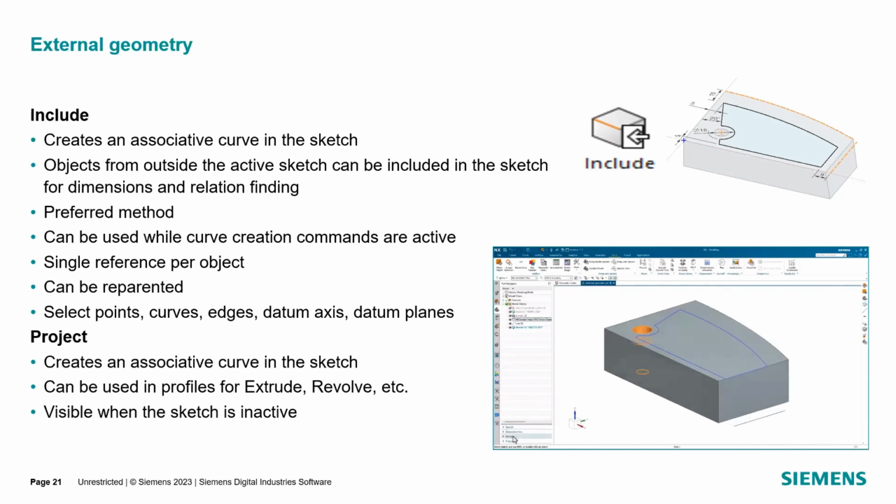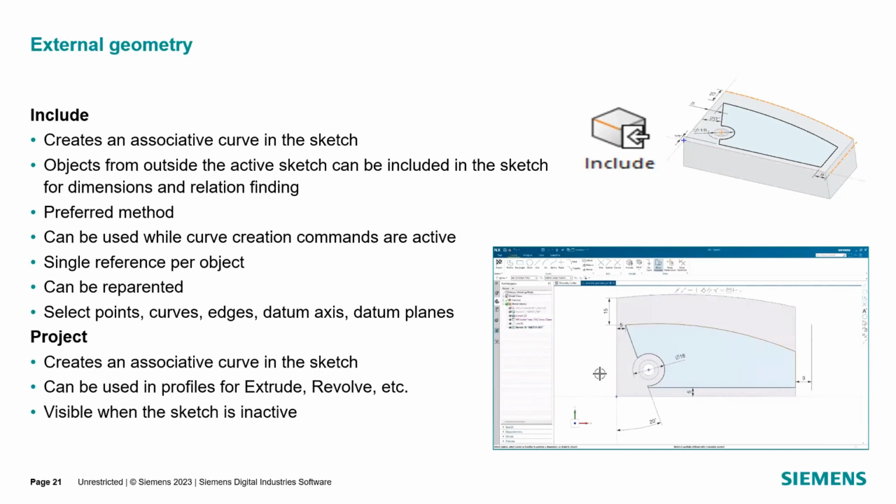We had dimensioned off of that. If we move the whole feature, you'll notice that your sketch is going to update. And that was the bigger clearance diameter that I had put on there. It stayed connected to the center point of that hole. So just some ways to help you as you do that, right? So keep that associativity to things that are outside the sketch.